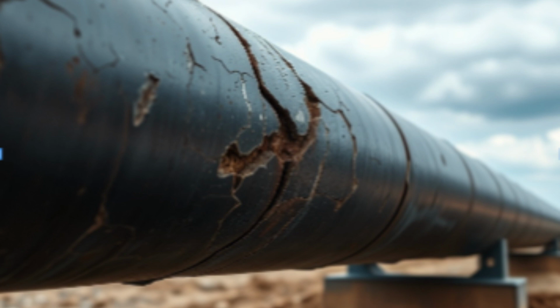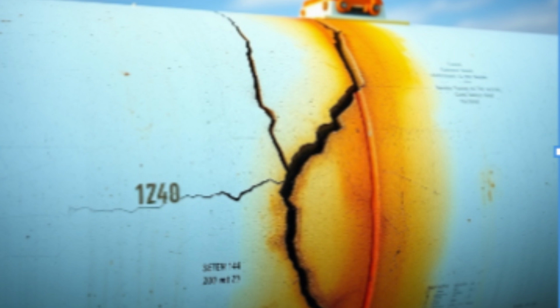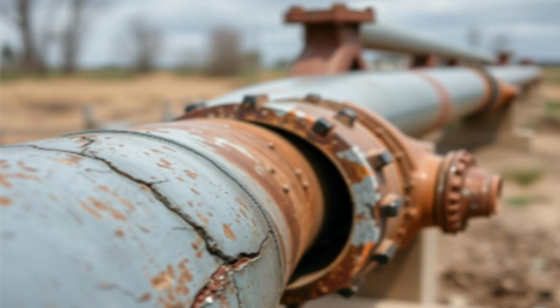Appearance. Creep stress typically appears as elongation or warping of the material, often around areas that experience continuous loading. In metals, the surface may show slight bulges, thinning, or even visible deformation in high-stress zones. Over time, creep can lead to small cracks or voids within the material, especially at grain boundaries. As the material continues to deform, these microcracks can grow, eventually leading to visible fractures or even complete failure.